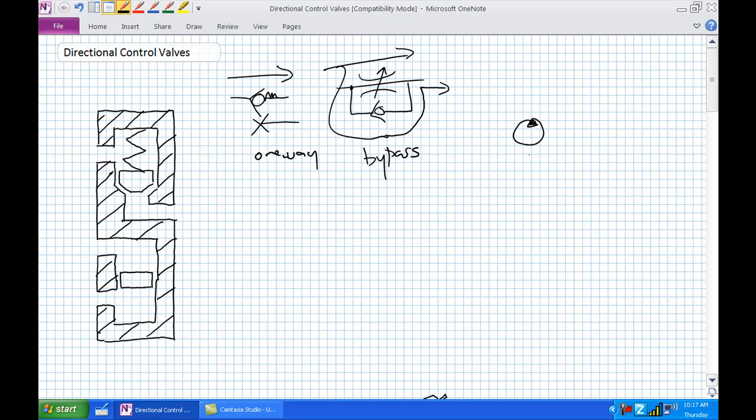Here's another one. Here's a pump. You expended all that time to get fluid into a passageway. Sometimes you could ensure that there's a prime, basically all that fluid that's been lifted up to here, so that when you turn the pump off, you don't want it to drain back through the pump. Basically, the check valve allows fluid flow in this direction, but stops it back in this way. So basically keeping prime.